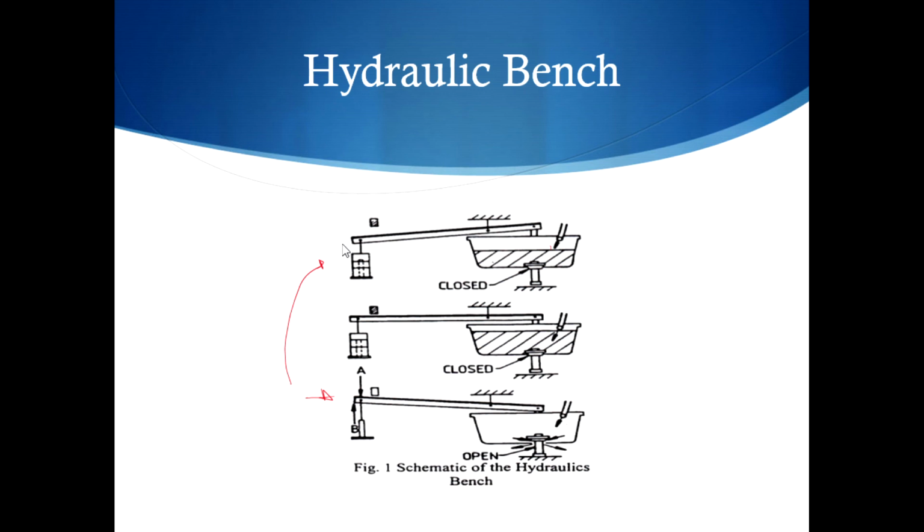So, for example, we are at 20 seconds and the weight is still down. When it goes up one time, it will go up very abruptly, and then it will go down again, and then it will go up again. The second time that it goes up, we have to stop our time. Therefore, we know the time in which water filled in here, and we know a known weight. Therefore, we can calculate our flow rate.